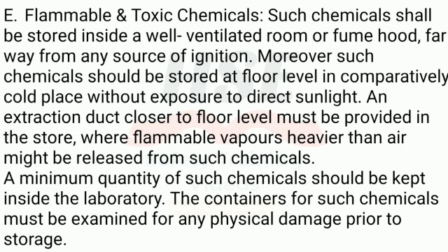E. Flammable and toxic chemicals. Such chemicals shall be stored inside a well-ventilated room or fume hood, far away from any source of ignition. Moreover, such chemicals should be stored at floor level in comparatively cold place without exposure to direct sunlight. An extraction duct closer to floor level must be provided in the store, where flammable vapors heavier than air might be released from such chemicals.